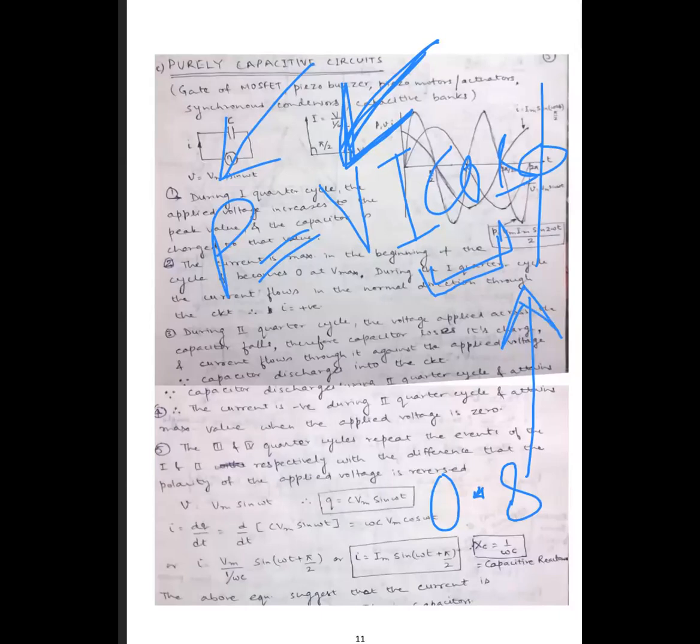0.8 is the acceptable limit, and if it decreases beyond that, it means that the loss of power is to be compensated by the current. So more current will be drawn from the mains. Okay, so when more current is drawn for the same power consumption, it is a loss to the nation. So the country applies penalties on less power factor. So how can it be improved?